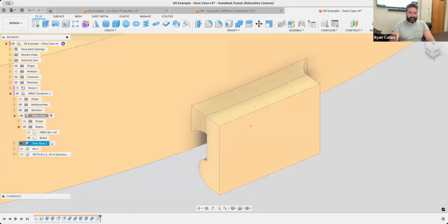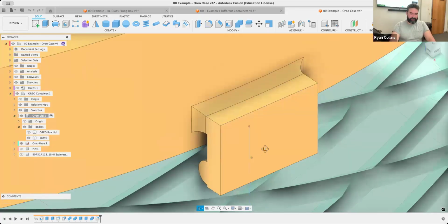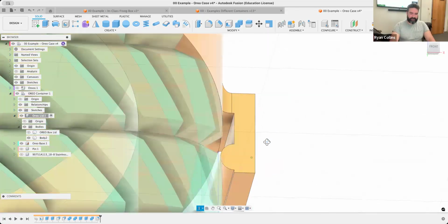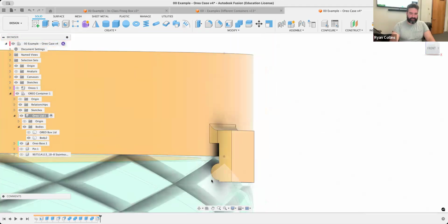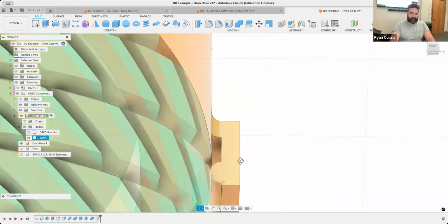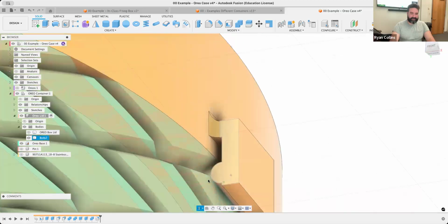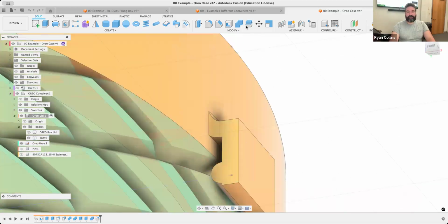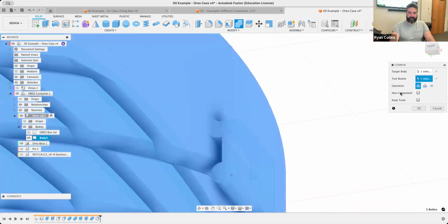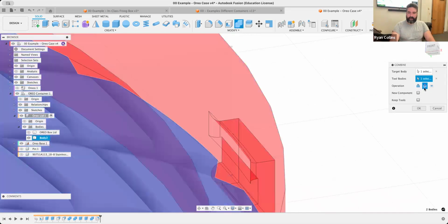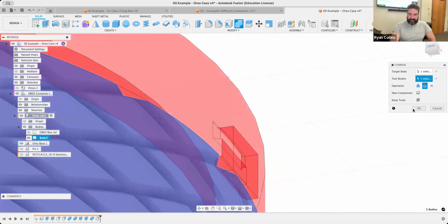Okay, that was excessive. So ultimately, the last thing I need to do here is add a cut into the bottom using the top. Because this is a curved body, I am going to run into trouble. So what'll happen is, combine, I want the cut to appear on the bottom and use the top as my cutting tool. I'm going to cut, and I want to keep my tools. That's extremely important because if I don't, the whole top will disappear.